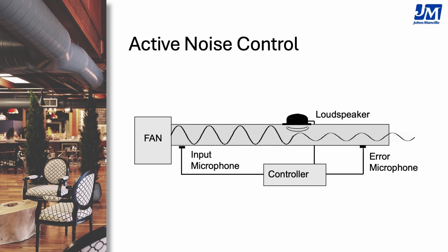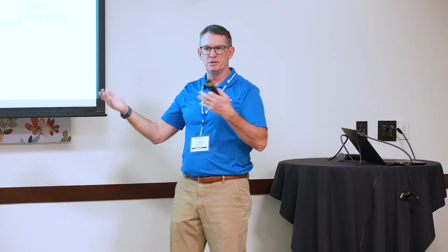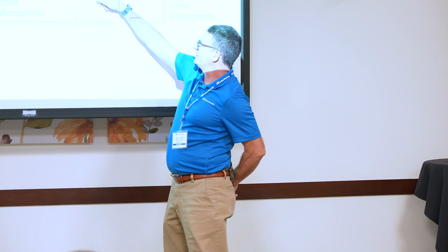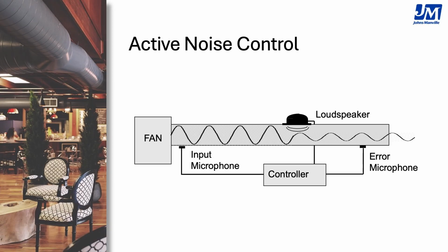And finally, last one on acoustics, what is active noise control? How does that compare to materials, things like that? Active noise control is truly just that. There's a couple of microphones, and they put a loudspeaker somewhere on that duct, and there's a computer controller, and it emits its own noise.